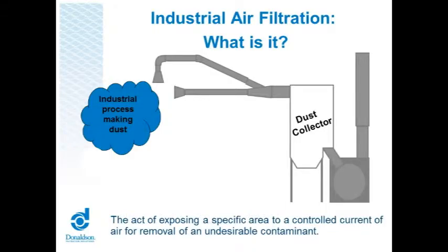So the first question is, what is industrial filtration? Well, basically, you've got a process making dust of some sort, whether it's a wood shop sanding pieces of wood, or a welding shop welding and capturing that smoke or fume that comes off of that process. What we do is we basically capture the dust at the source as best we can. We convey that dust through pieces of ductwork, and then we collect it in what we call our dust collector, and the fan is at the end on the clean side, typically pulling the negative pressure that allows us to capture and convey that particulate.